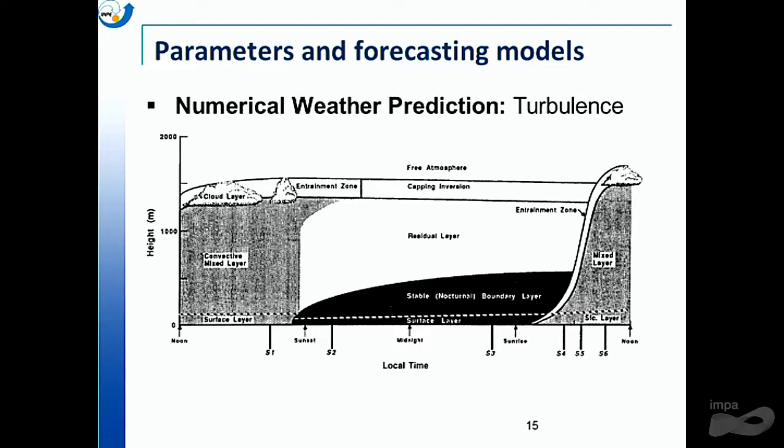However, this eddy diffusivity here is a little bit different from what we are, in general, dealing with, for example, with diffusion. Diffusion could be characterized by a material property. But here, in turbulence, this eddy diffusivity is not a material property, but a property of the flow. And so if you have different flows, you are going to have different eddy diffusivities.